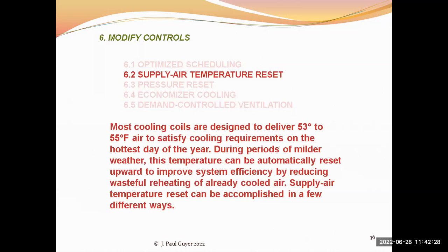But during periods of milder weather, this temperature can be automatically reset upward to improve system efficiency by reducing the wasteful reheating of already cooled air.